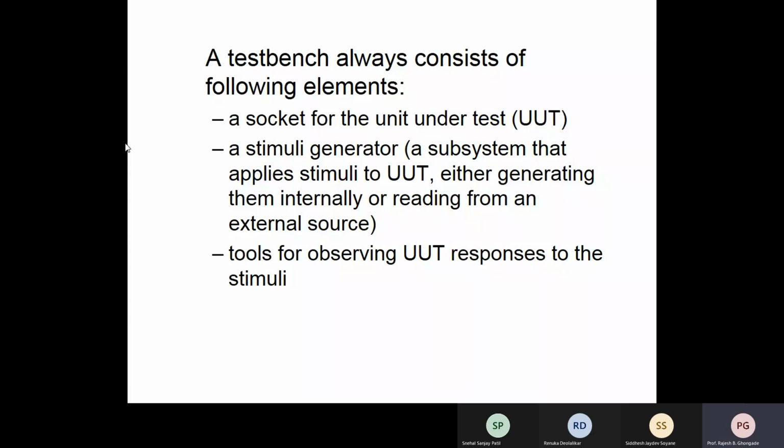What I did was I created a circuit, basically an oscillator, and gave the output of the oscillator to the audio amplifier card and checked its output: whether the frequency response is proper, whether the audio output is up to the required level in decibels, and so on. So the concept here has been borrowed from the hardware industry; it is called a test jig.